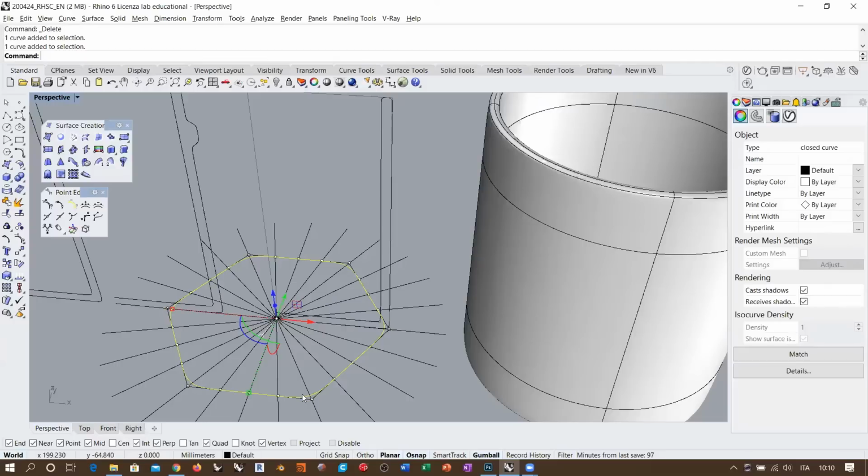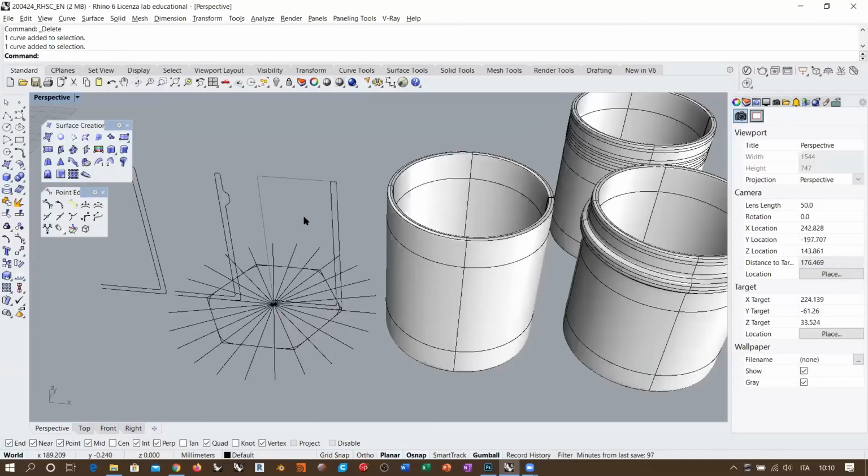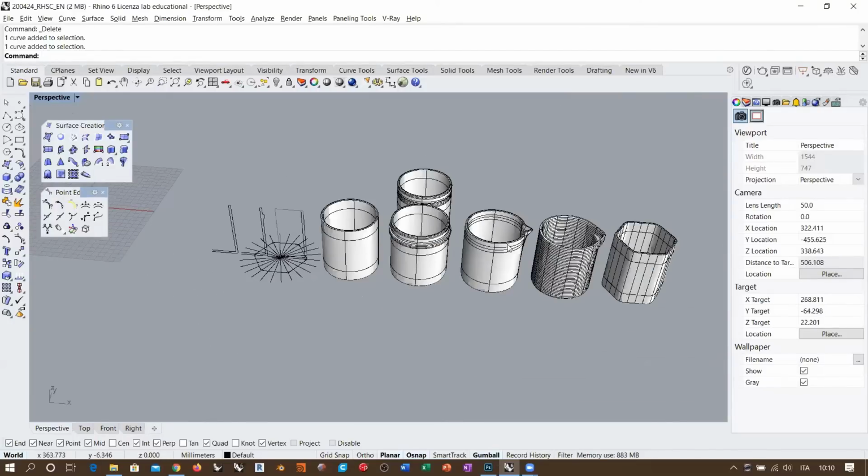But if you smoothen the curve and create it with a degree 3 curve, which by default has no internal kinks, and so no internal discontinuity, visible or invisible, then you will get a perfect degree 3 smooth surface.